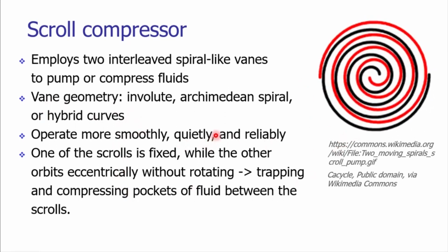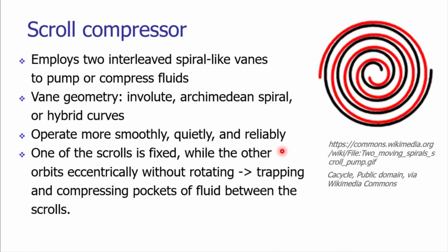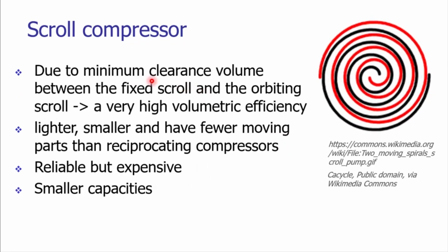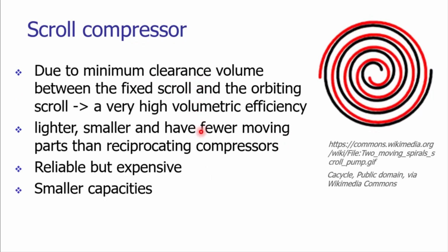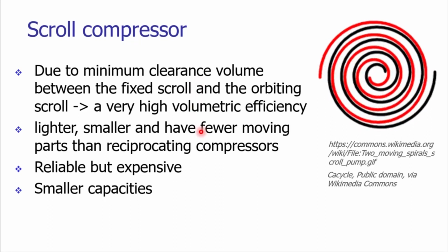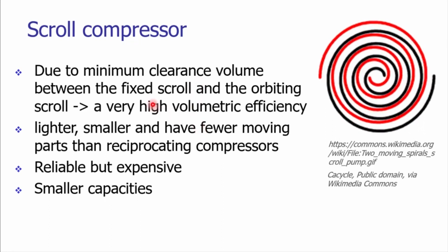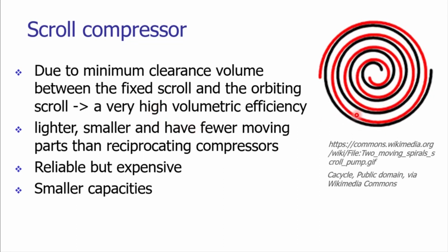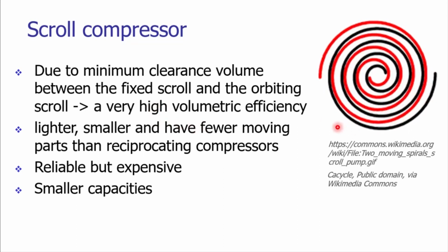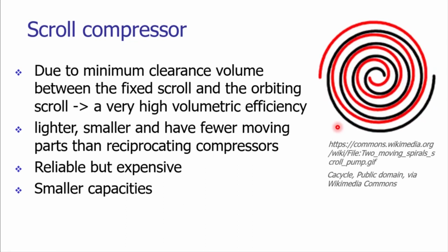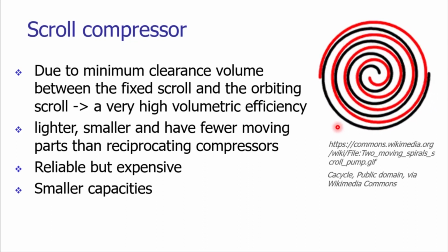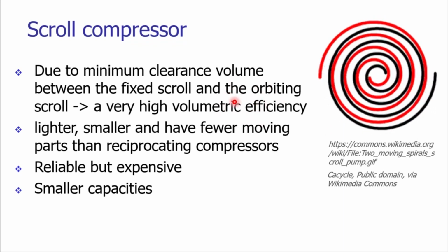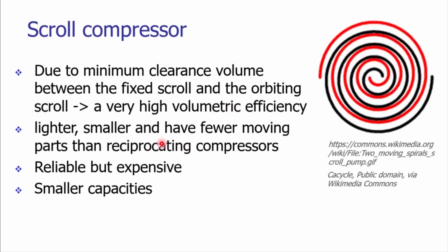The operation of the scroll compressor is smooth. The operation is quiet and the reliability of the scroll compressor is quite high. Due to the very small clearance volume between the fixed scroll and the orbiting scroll, scroll compressors offer us high volumetric efficiency. As the clearance is less, the leakage is less, therefore the volumetric efficiency of the scroll compressor is quite high.